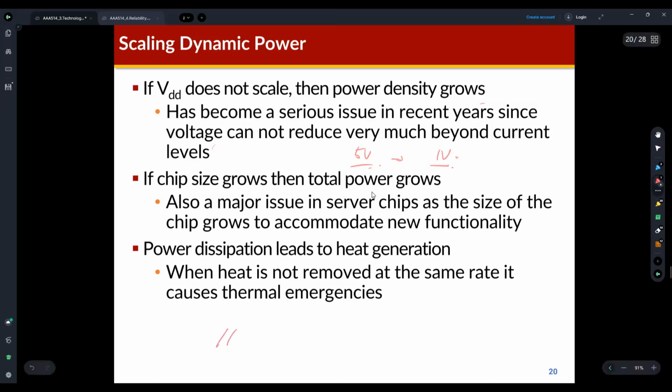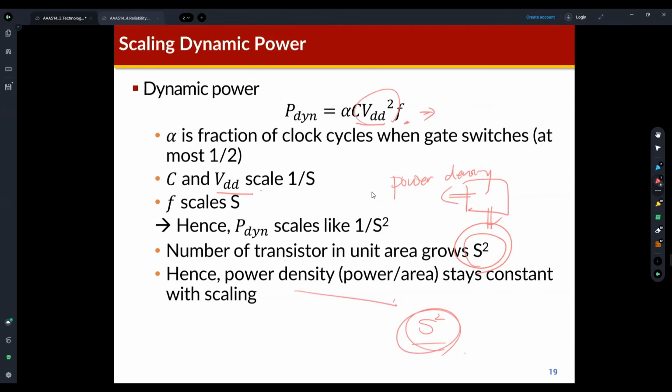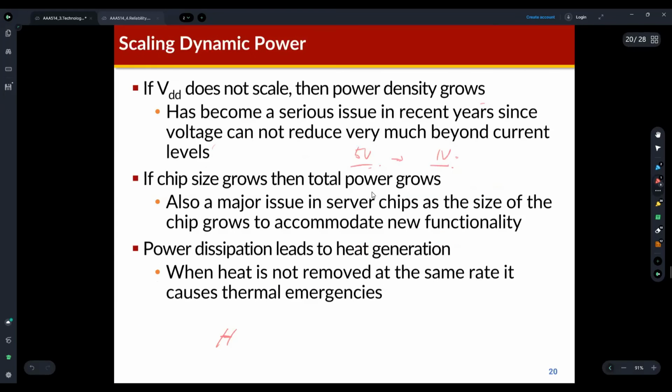The benefit of the CMOS scaling is that the channel length is reduced, so we can make a better device. Also the benefit of the CMOS scaling is that we can reduce the supply voltage, but this supply voltage is also influenced by the threshold voltage and other factors, and we need to consider different factors of the power consumption. Then we cannot reduce this supply voltage level more dramatically.